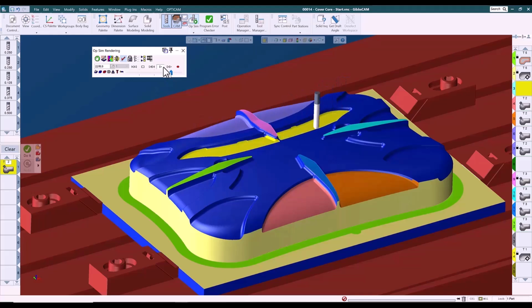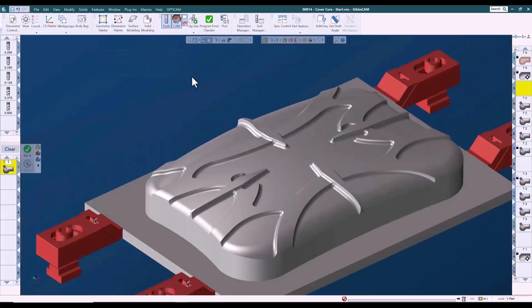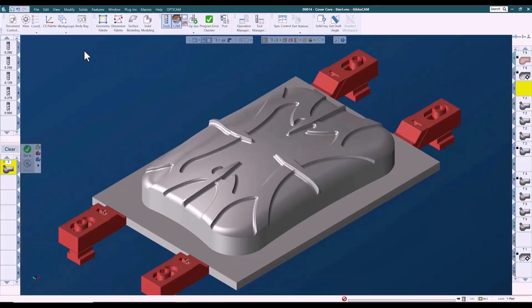triangle mesh, which is the strategy most widely used in the industry, since the toolpath is a little simpler to calculate and it calculates a little more quickly. But toolpath can also be calculated based on the actual surfaces or based on a geodesic mesh, which tends to produce a smoother, more consistent toolpath.